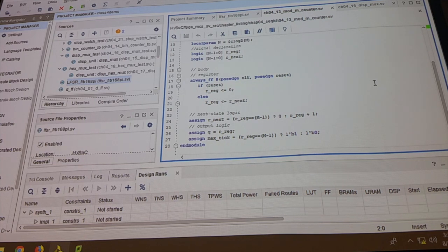It can infer from the plus 1. Well, from the plus, it can infer a counter. Right, and there's pre-built hardware for counters inside the system, so it usually infers one of those pre-built counters within the system, so you get a very nice fast circuit. So this is actually really good synthesis right here for our systems.